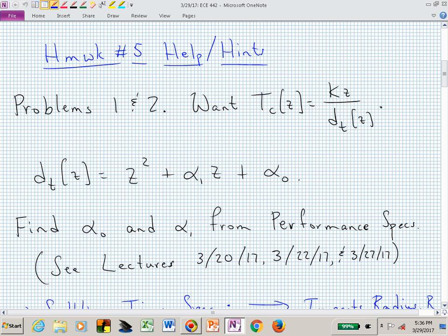And in some cases, you may have a lot of freedom. Maybe I give you a settling time specification. So settling time, what do you see with settling time? Geometric shape. Circle. So now if you have circles, and you only have circles, now what do you do? You're trying to find 2 points so that you can find an alpha 1 and an alpha 0, and all you know is the radius.